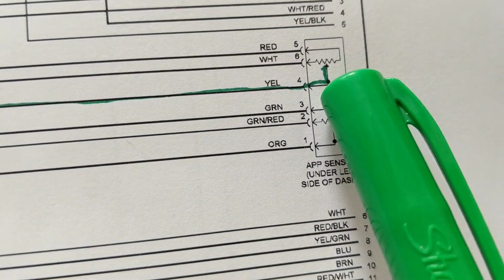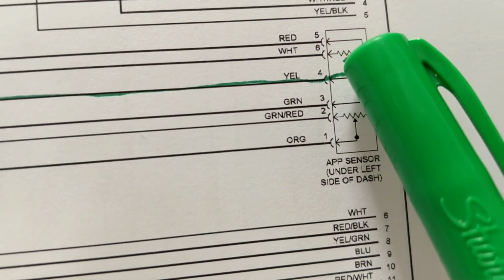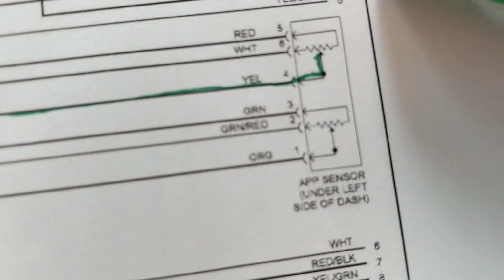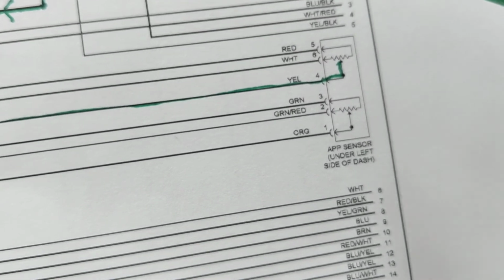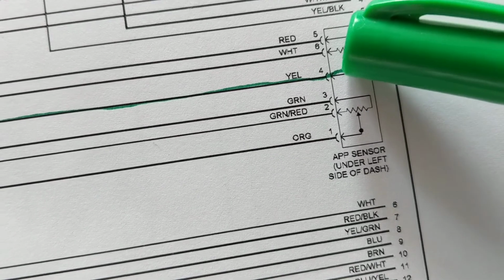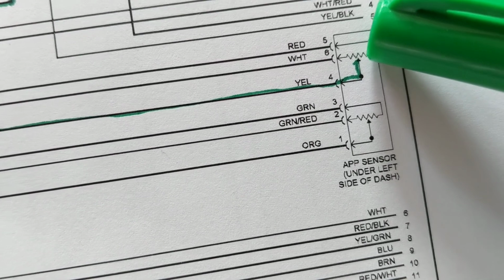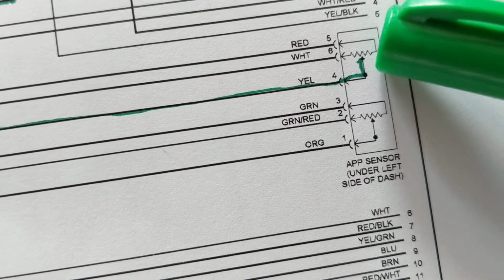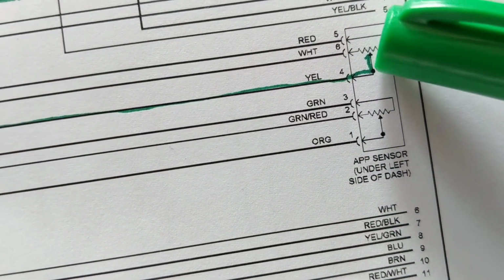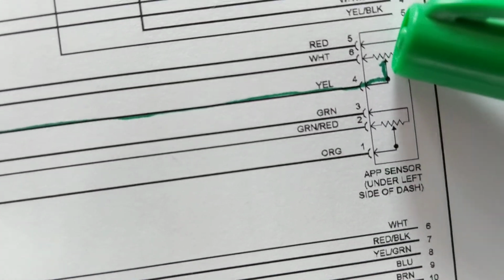Whenever you see this, we learned before, this is one sensor. This is a potentiometer. It's a resistor, let's say, that you vary, that you change. Over here, you're changing the voltage. The middle one is called the wiper. You're sliding it back and forth. At one point, you're at 5 volts, because the reference for this is 5 volts. At another point, you're at 0 volts. When you're at the midpoint, you're at 2.5 volts, half of the reference voltage.